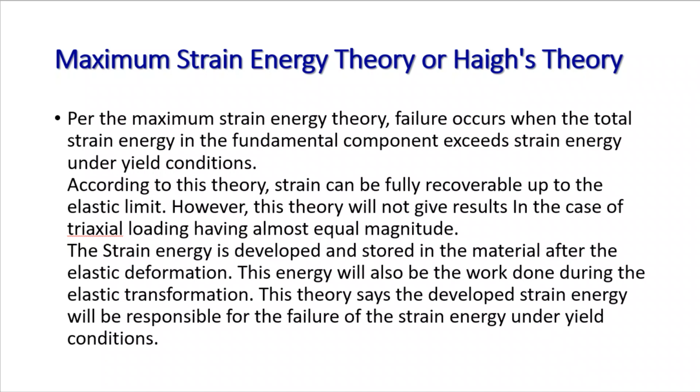The next theory is the maximum strain energy theory, or Haigh's theory. As per the maximum strain energy theory, failure occurs when the total strain energy in the fundamental component exceeds the strain energy under yield condition. According to this theory, strain can be fully recoverable up to the elastic limit. However, this theory will not give results in the case of triaxial loading of almost equal magnitude. So the strain energy theory is developed.